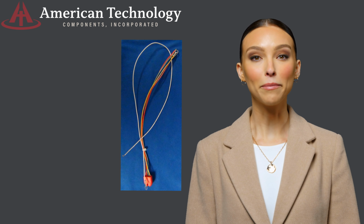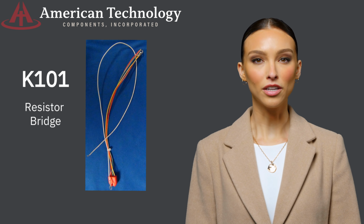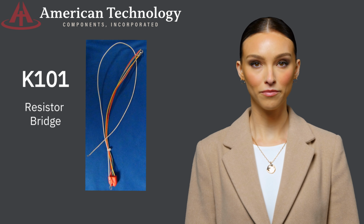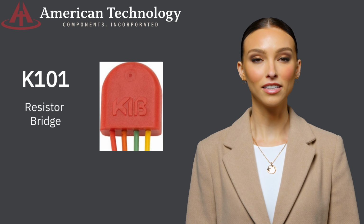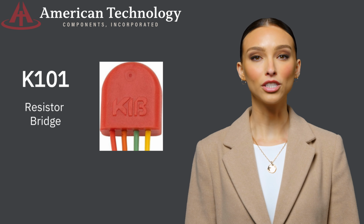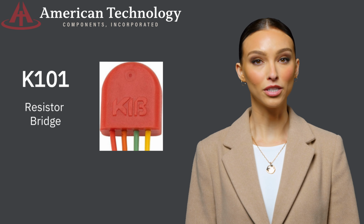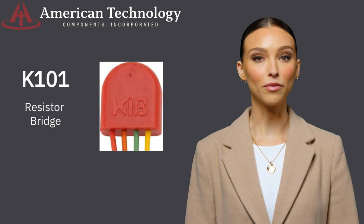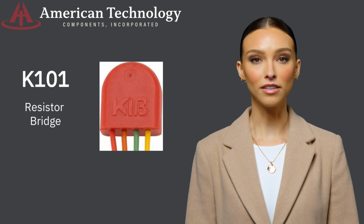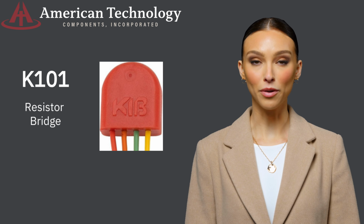This is the most commonly misdiagnosed component in the system. Attached to every tank to be measured is the K101 resistor bridge. Many people will refer to this as a sensor or diode pack. Neither of these descriptions are accurate. The construction of the K101 is simply 2 resistors with 4 wires connected at strategic points to provide a pathway for voltage to produce a specific result from a reference voltage from the associated monitor panel. The resistors and connections are encased in plastic for the protection of the components from corrosion. There are no serviceable components with this K101.